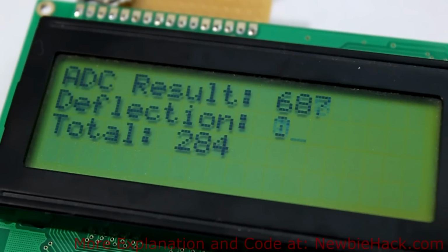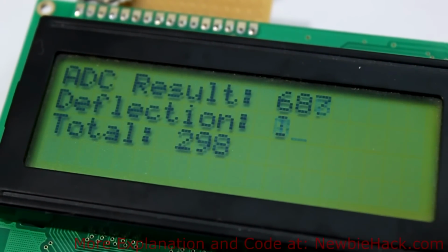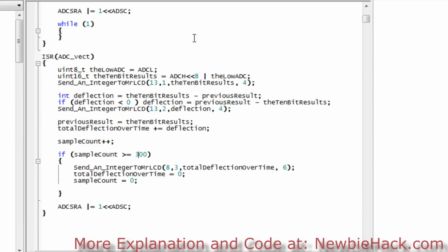Now we're going to look at putting the ADC in sleep mode and see if that helps. There is a noise cancelling technique that is recommended by the datasheet to put the microcontroller into a sleep mode while there is a conversion going on, because there are about 3 different clocks running inside the microcontroller that are essentially really noisy to a lot of the functions.